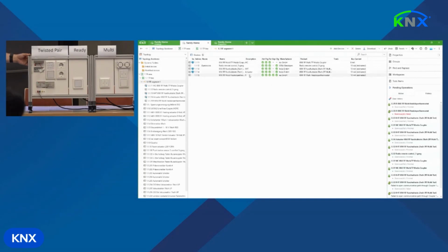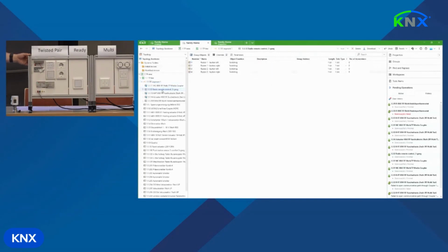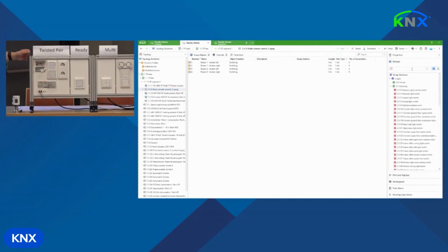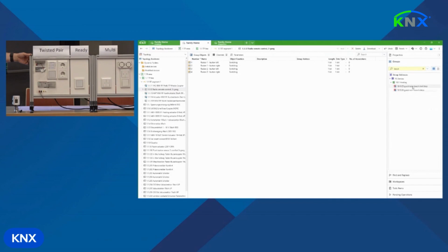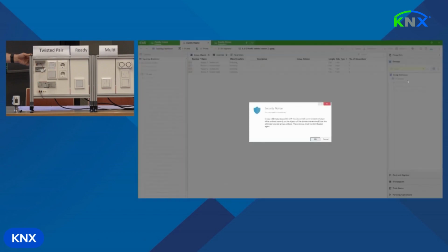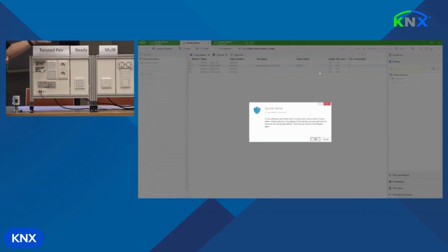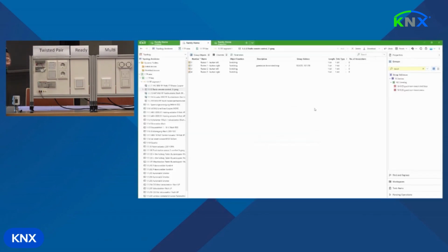We removed the control of the ceiling light from the first button already. So let's use the second one to control something from this SLE device. Okay, so I see I already have prepared 2 group addresses for this purpose. Just use them. So it will tell me that these group addresses will work unsecure. Exactly. They have been used outside this RF segment in a secure way so far, and as we're now linking them to the radio frequency ready device, not being able to do this securely, the security needs to fall back to plain communication.